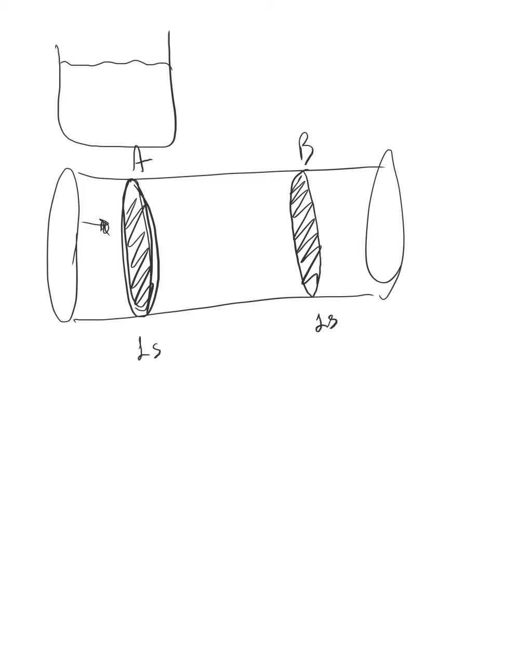If you think about it, this law is easy to understand. Let's say we had more liquid going through section A, and less liquid going through section B in the same time. Then there must have been some sort of collection of liquid in between.